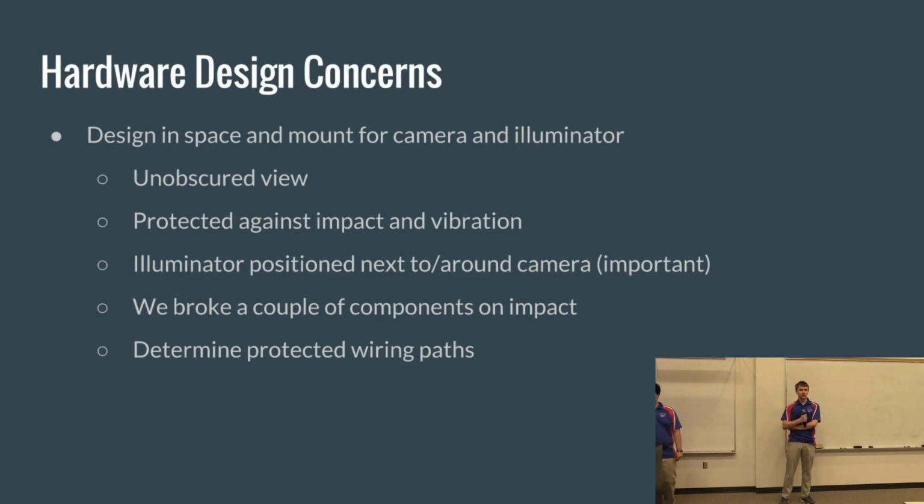When they take hits, they need to not get moved or shifted, especially in the case of the camera. If your camera gets bumped even slightly, your longer range shots are going to start missing just ever so slightly. We got tripped up at Worlds because of this. Our camera was slightly bumped after a match, and our shots kept bouncing off the left edge of the goal instead of going in. And then you need to make sure your LEDs are properly secured.